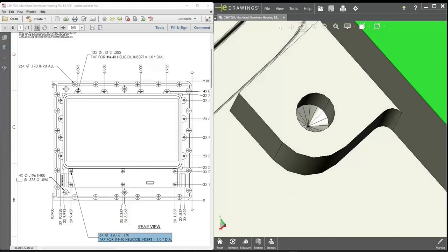But staying on the helicoil for a minute, because we've got 6 in this location and we've got 12 running around the part. So at a quantity of 100 relative to our total fabrication, and we do the math, we've got 1,800 holes. So from 2 perspectives, one is the machining of this hole, and the faster we can machine the hole and the more efficient we can do that, clearly we're going to save time.